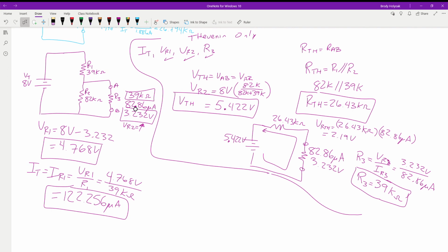If we got a smaller number than that, we did something wrong. Somewhere along there we could have typed in 3,900 instead of 39,000, and that's where we could double check our answer, because it's going to be way off. If we fat fingered it, we could have 12 microamps going into the circuit where we need 86 to meet these conditions.